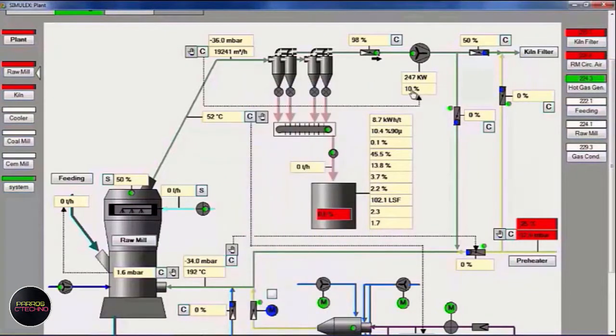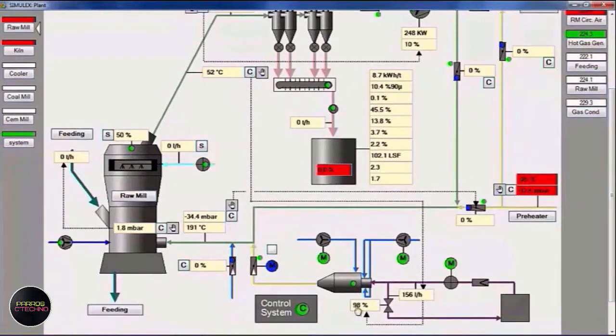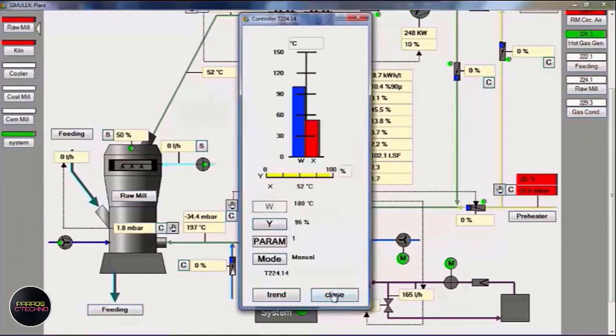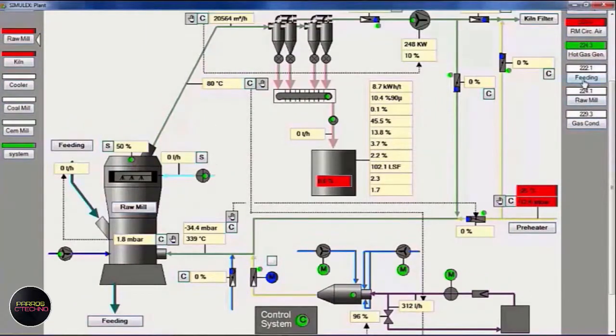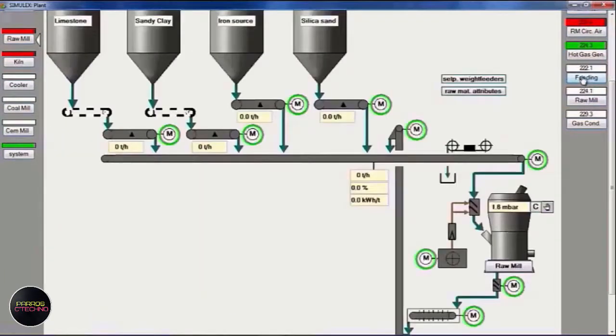We add another 2% of the oil usage. The oil usage has reached 310 liters per hour. Then the temperature for the inlet is around 340 degrees Celsius, the outlet is 80 degrees Celsius. We first prepare to run the feeding system. What is meant by group feeding is not the material that will be included, but the bucket tailings reject material, meaning that the coarse material will be milled back into the mill later.